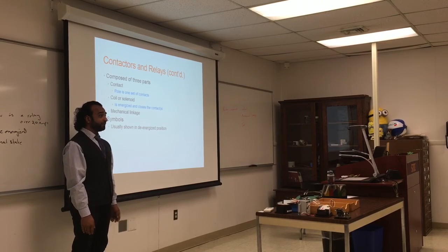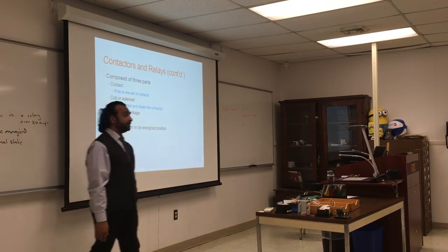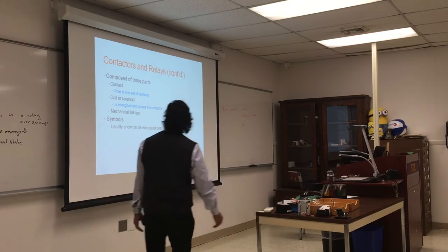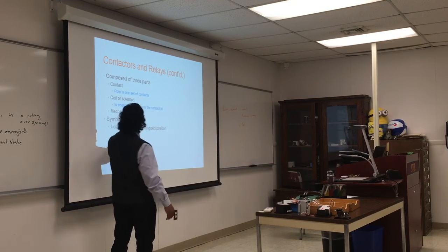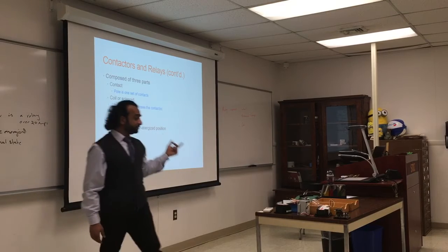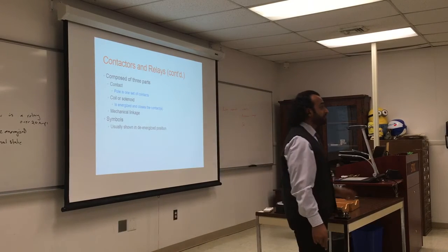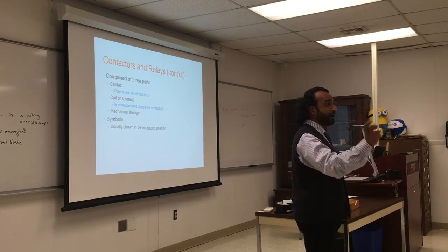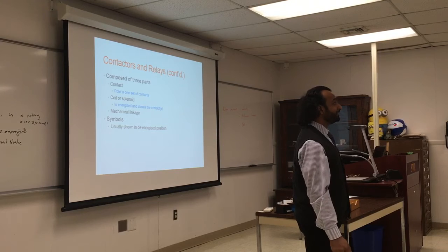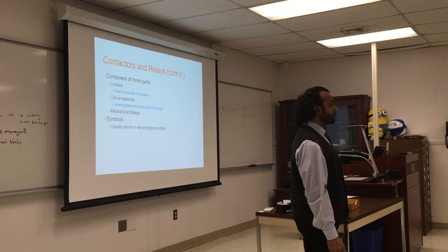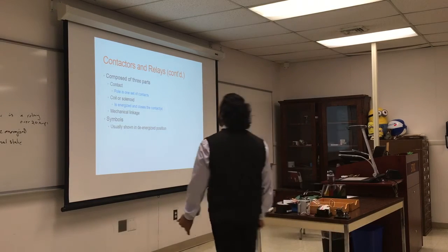It gets overheated, it rusts, it gets cut out. There are many reasons to burn out. Then there's the mechanical linkage, that's the armature. It just breaks. That's easy. If you check a contactor and you hear rattling, the linkage is broken, so it has to be replaced.